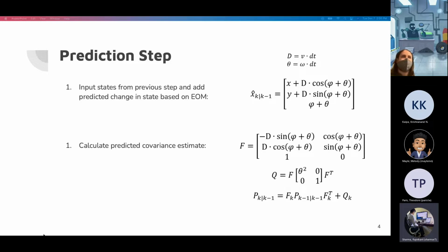So filtering the data real time was okay, but there are also processes in place, for example, using some kind of chi-square test on the residual. If your residual is bigger than some threshold, then you don't use that measurement. That's definitely what we would do if we were to continue on: look into different methods of filtering. I think it was a day or two before we realized that our measurements were the problem. If we had a lot more time to research how to best deal with that, we could have had a much better result. But yeah, you'll be fine.